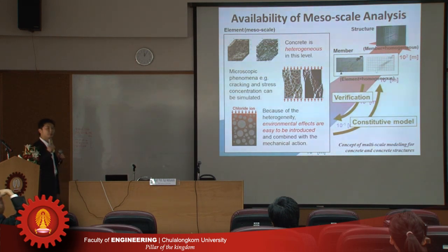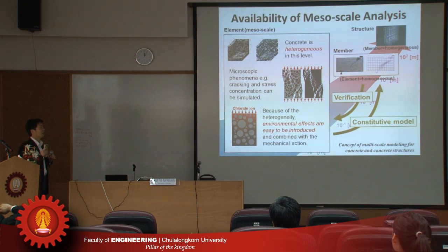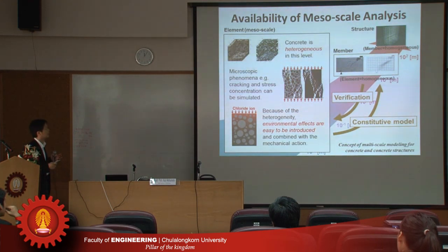It means that we assume this concrete element behaves homogeneously. However, concrete itself is actually a heterogeneous material because it is composed of aggregates and mortar. So in mesoscale, we treat concrete as a heterogeneous material composed of aggregate, mortar, and sometimes different components as well.